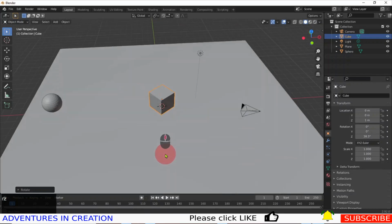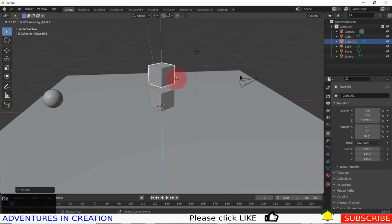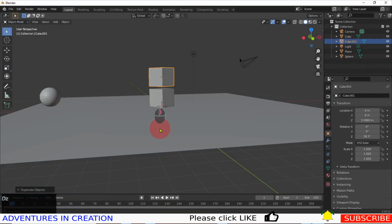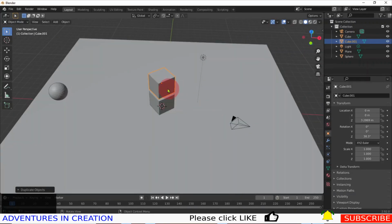Now what we're going to do is add a second cube. So Shift D for duplicate and Z to go up. And we're just going to sit it up in space. So it's sitting up in space at the moment. The reason I'm doing that is because when you do these animations, if you have them overlapping, when you turn it on, it will jump up in the air because it will try and react to the fact that it's overlapping, because you can't overlap in space. So it really does that. So I'm going to take that cube and rotate that one in the Z axis. I'm just going to turn it a little bit